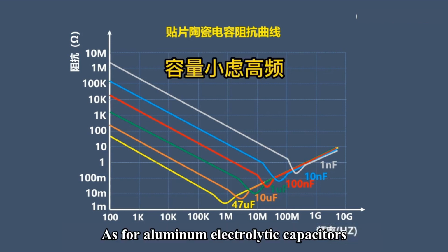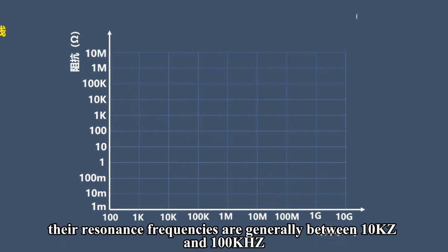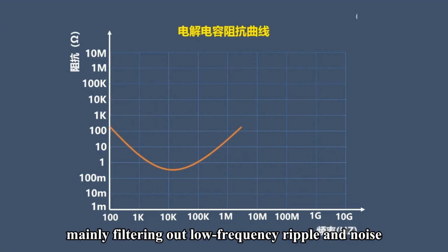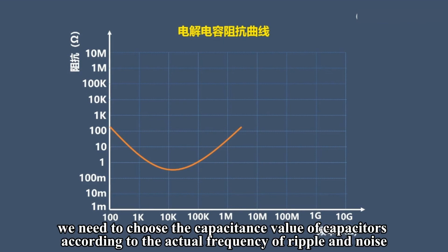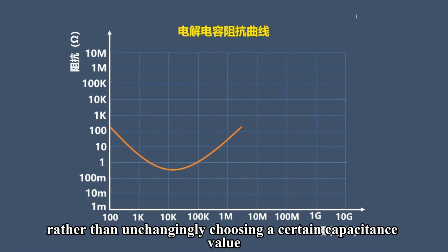As for aluminum electrolytic capacitors, their resonance frequencies are generally between 10 kHz and 100 kHz, mainly filtering out low frequency ripple and noise. Therefore, when filtering the power supply of chips, we need to choose the capacitance value of capacitors according to the actual frequency of ripple and noise, rather than unchangingly choosing a certain capacitance value.